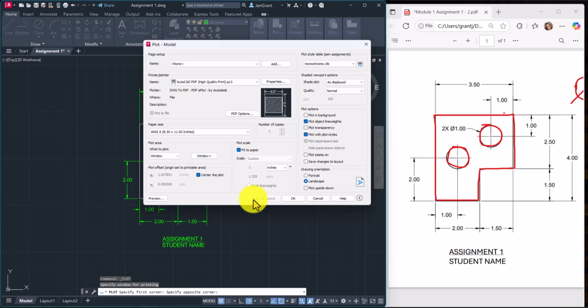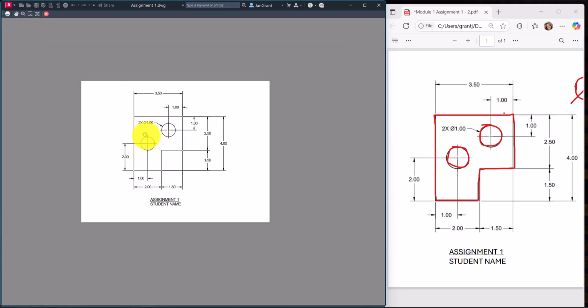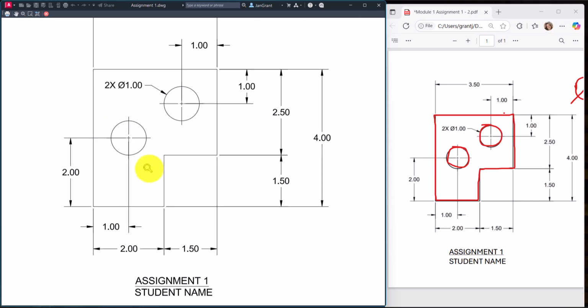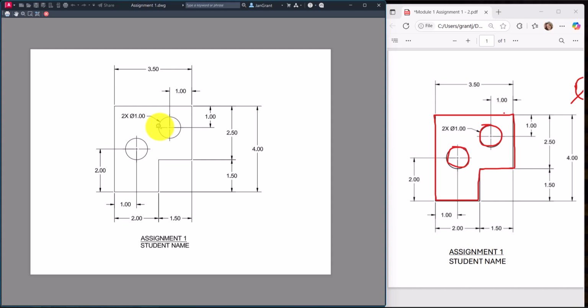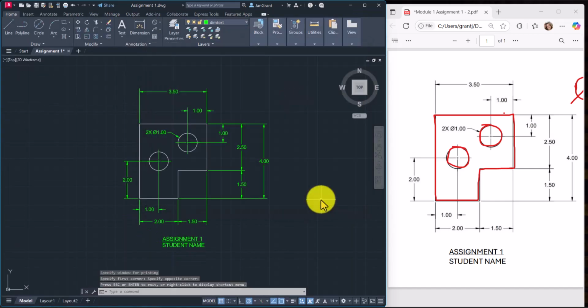And now we always want to pick preview at the bottom left. It should show you what your drawing looks like. And oh, good point. I did not change the line weight of the objects. You see how this is lighter? We don't want that. We're going to go back and do that now. Usually we'll pick that up when we're creating layers, but this is a good thing because if you roll your wheel and you don't see line weight difference, you know you didn't set it up. So now use your escape key to cancel out of this. Don't print it, but it's saved, right?